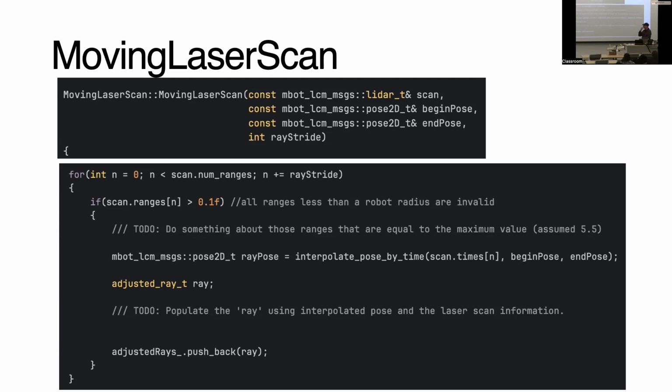Yeah, no. So in the next lecture, we're going to look at localization. And so we're going to look at being able to figure out how good an estimate of a pose is by looking at the sensor information and whatever map that we currently have. And so when you add these two together, you basically iteratively just update your map and then update your location. And then you update your map again using the location you just found, and then you update your location using the map you just found, and so on and so forth. And that is simultaneously localizing and mapping. So that is going to be our full SLAM system.